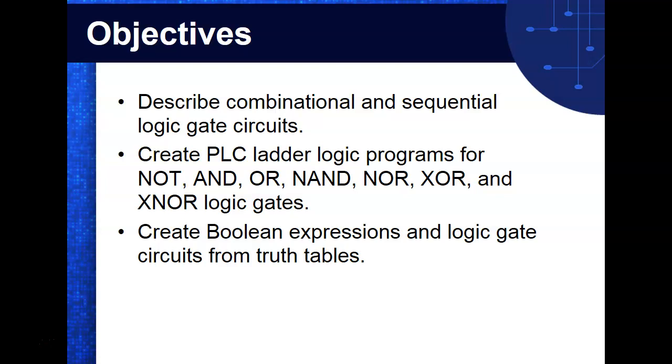And what you do, guys, is that you don't... this right here is a symbol. Now, we learn it as what? Plus, because we know math. But in USB, it's the non-inverted signal. So USB uses what we call differential signaling. So it sends the signal 180 degrees out of phase. So if it was sending digital information like this, then the minus wire would be carrying the opposite of it. But we learned it as math.